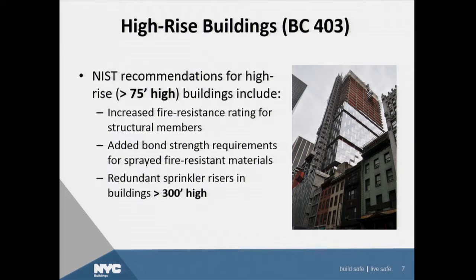All right, for high-rise buildings that are in excess of 75 feet, and just so you know, this doesn't apply to, I believe, air traffic control towers, if anybody's out there designing one. It doesn't apply to R3 occupancies, which is one-family. And sometimes we do get high-rise one-families. But a lot of that was already in the 2008 code.